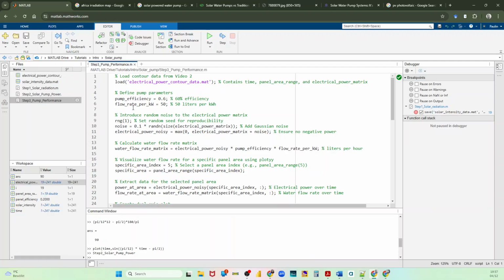And the last step takes the solar radiation from the previous video, takes the solar pump power in kilowatts from step 2, and now works out the pump performance. We're not talking about a specific pump, it's just really trying to understand it. And more importantly, what variation can we expect? Again, the loading function is what we talked about from step 2, and some efficiency and flow rate.